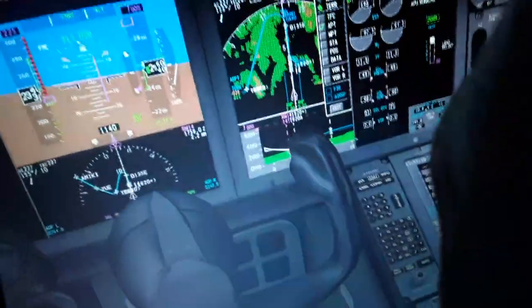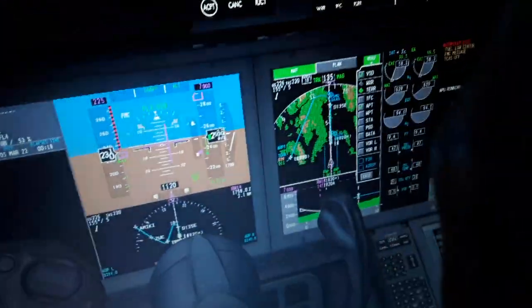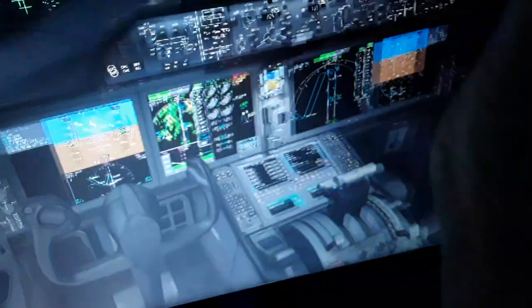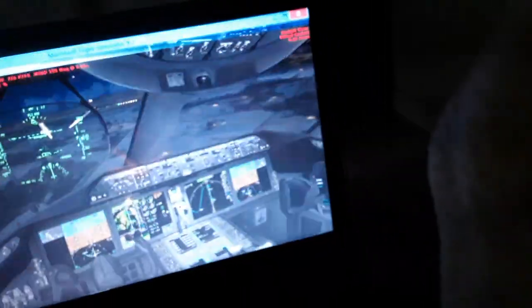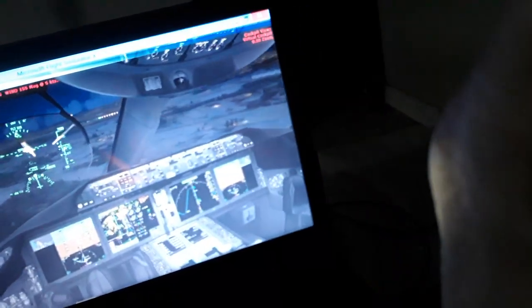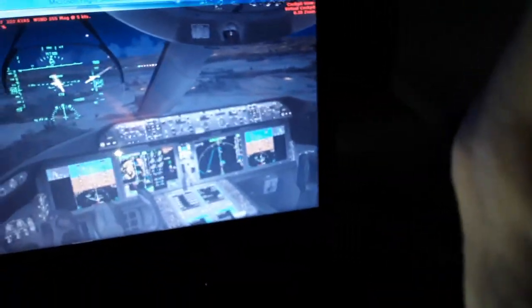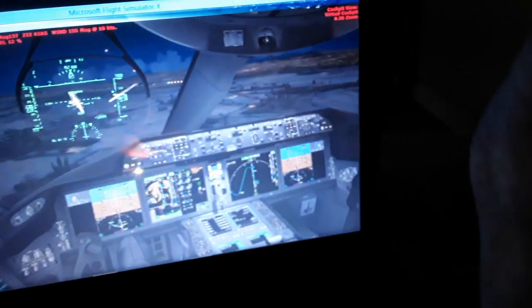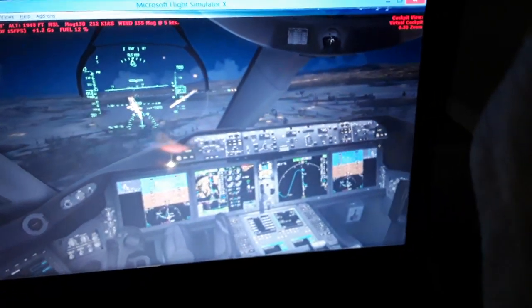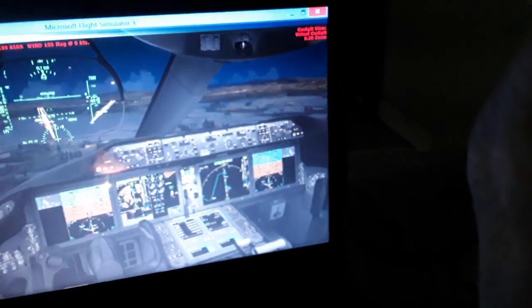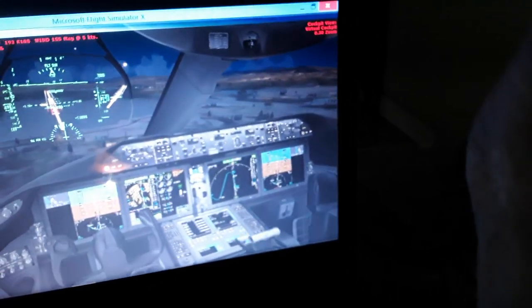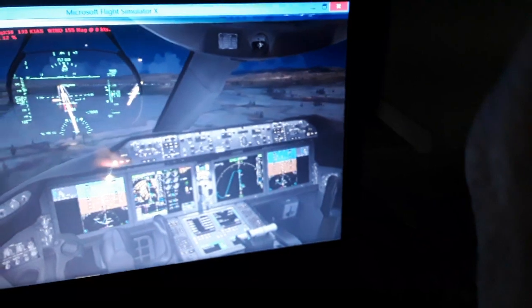So we have also the LSZH localizer here. We can use the LSZH localizer for alignment for approach and landing. We are a little bit higher in the LSZH localizer, so we need to increase the rate of descent. As you can see, increase a little bit the rate of descent, a little bit more airspeed now, increase again the rate of descent.